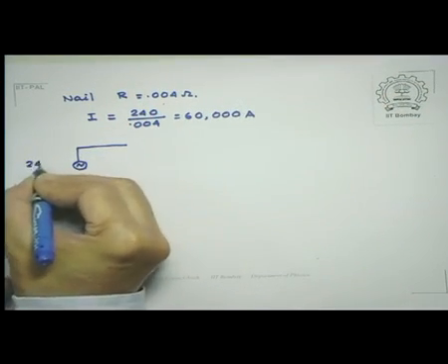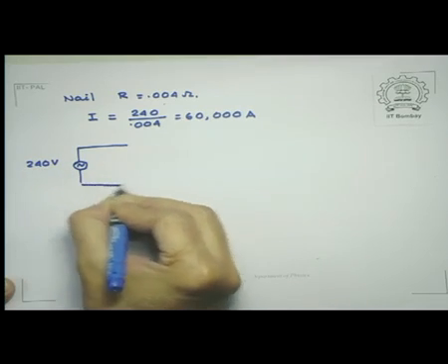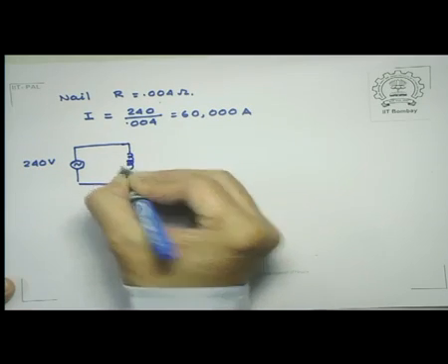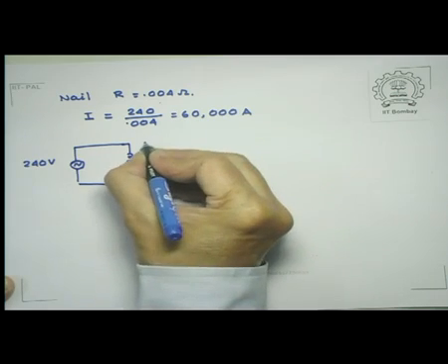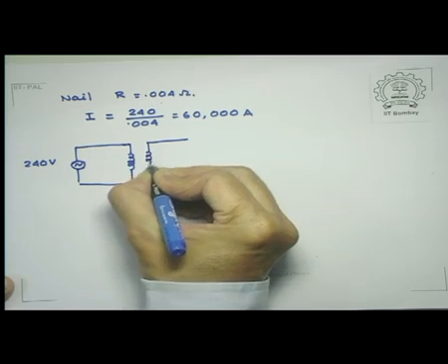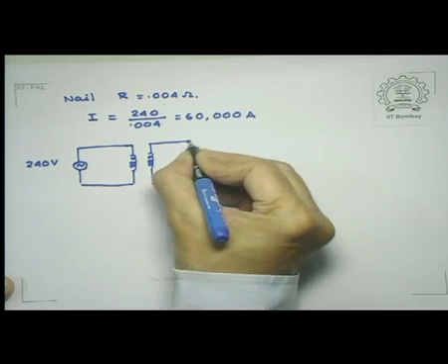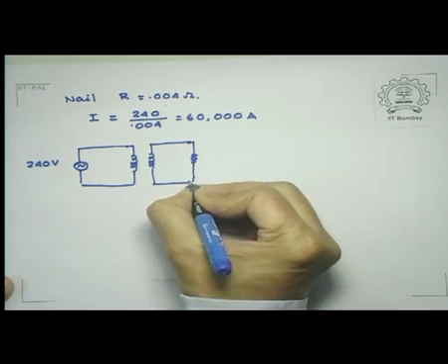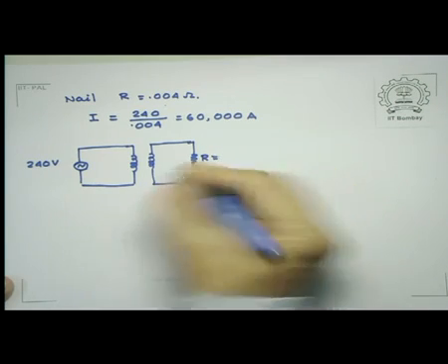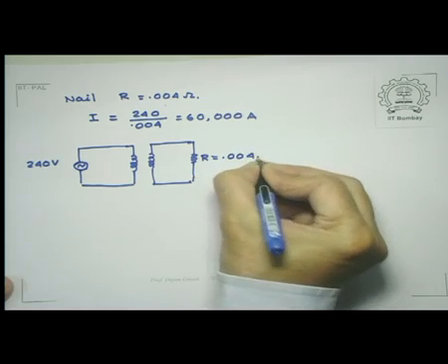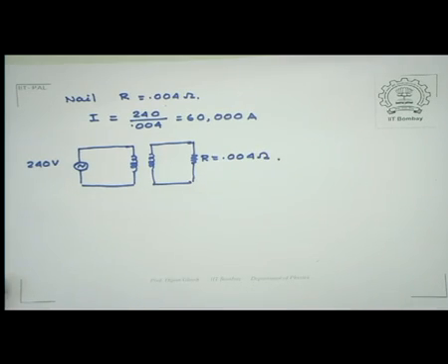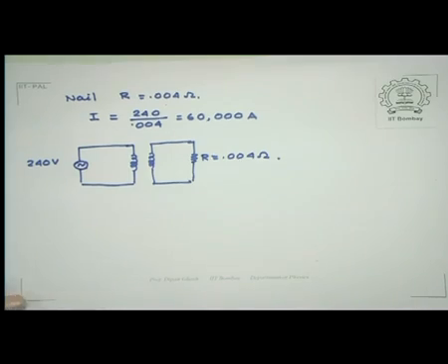Supposing this is 240 volt mains, I will work out what type of transformer you actually need. So this is the secondary circuit which is connected to the resistance that we talked about. Now the way to do it is the following. I calculate using properties of this piece of nail, like its mass, its specific heat, etc., and find out how much heat I need to melt this over a certain period of time.